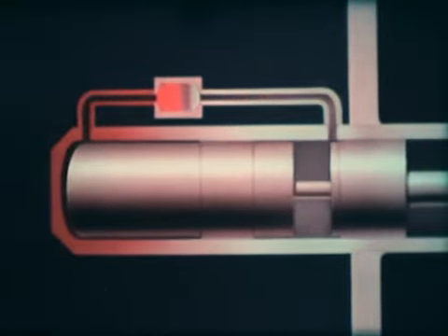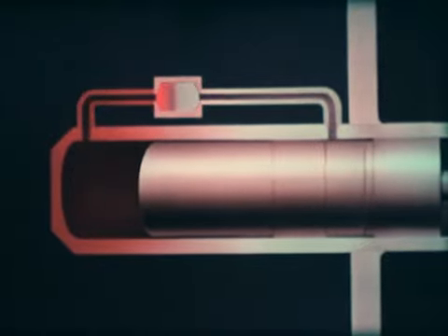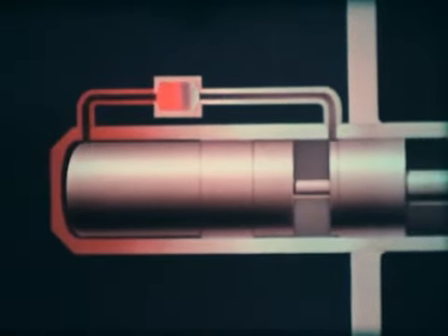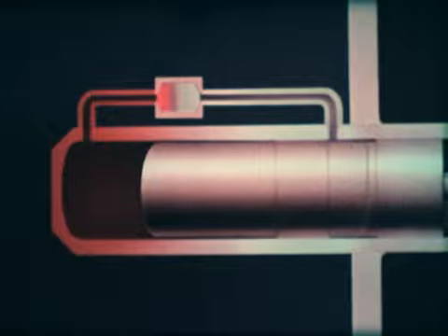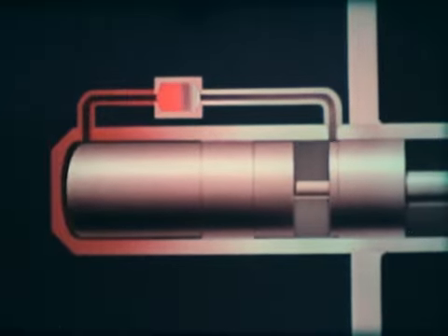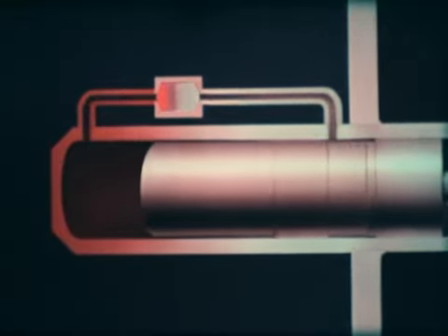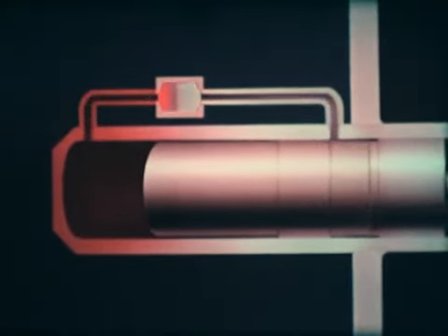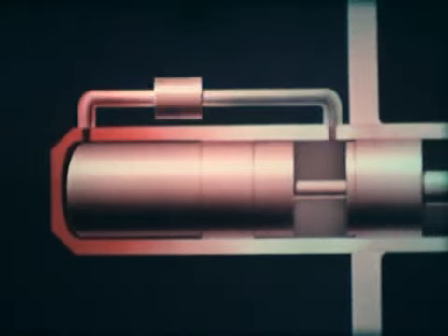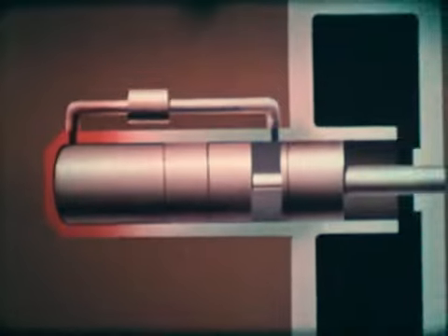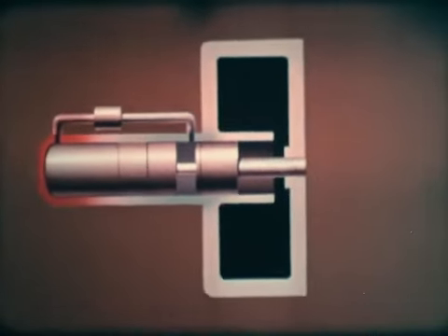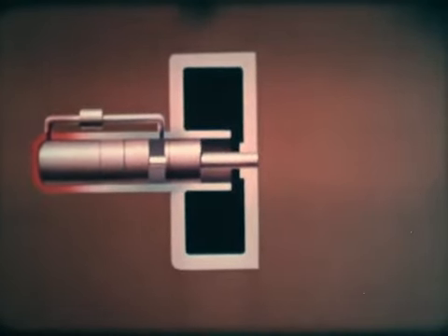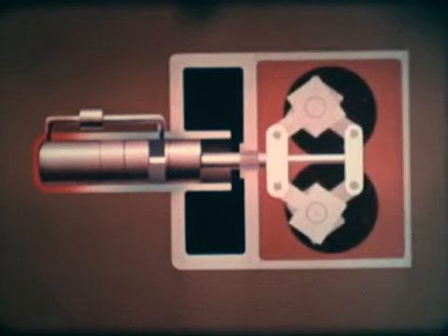The efficiency as well as the power is increased still further by raising the expansion temperature and by using hydrogen or helium as a working gas instead of air. The movement of the displacer piston is regulated by the power piston. A solution outstanding for its simplicity was evolved at Philips. It is known as the rhombic drive.